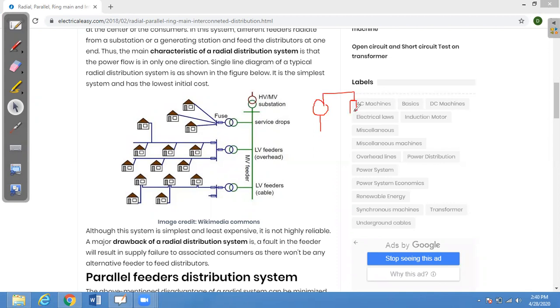If, for example, this is L1 and this is L2, and this is a supply V, you see all the loads are being fed from a single supply, that is V. So if we have any fault on this supply or in these connections, there will be a complete blackout on this whole load. This is L1 and that is L2. So this is basically the radial system.